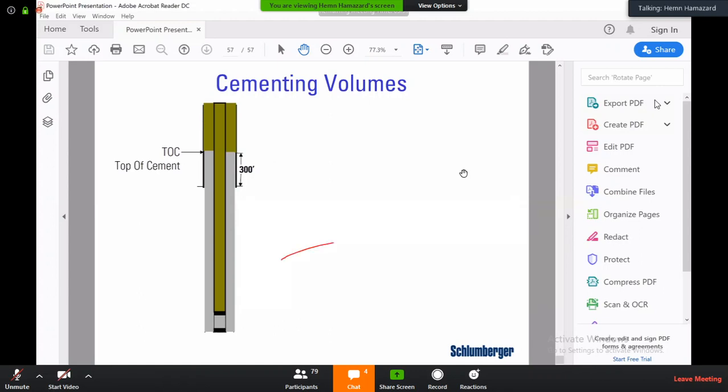Usually, the problem with a casing depends on many factors. For example, if you see that your connection has a leak, or you've already made a connection between two joints of casing but you are not happy about them, or you see a sign of a leak or something like this, it depends. If you are close to bottom, probably the company just tells you to go ahead and set your casing and cement it. If you have run only, for example, 10 joints, it's easy to pull out those 10 joints, find and troubleshoot the problem, and then rerun.